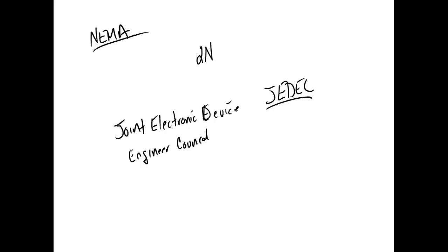So that TO3 pack, that's a transistor outline. TO3 is a JEDEC registered pack. Anybody can make that. So no matter what it is, whether it's an integrated circuit or a bipolar transistor or an SCR, if they put it in that package, and I'm developing a circuit card, I can pull in the mask for a TO3 pack, and I can make the circuit card for those. So instead of me making circuit cards and masks and everything, I can make the part and use a standard package, and then somebody else can make the circuit cards, right? You understand? So I can make the refrigerator and let somebody else worry about the cord.